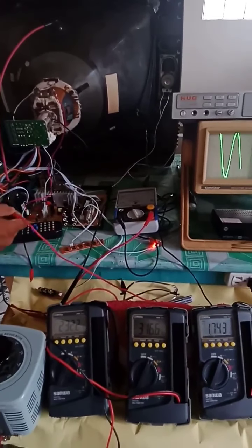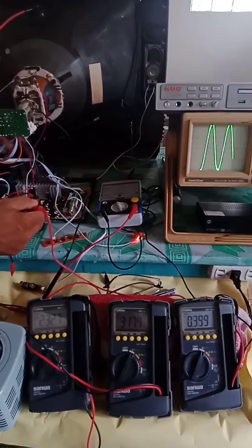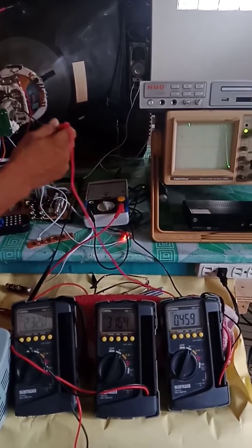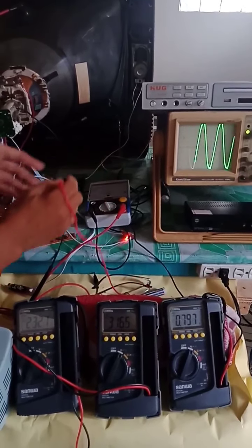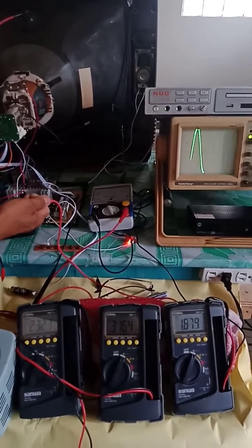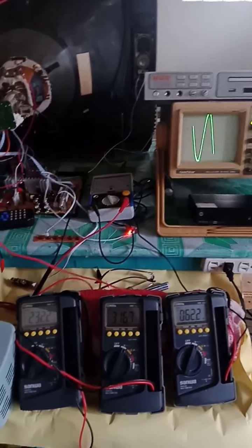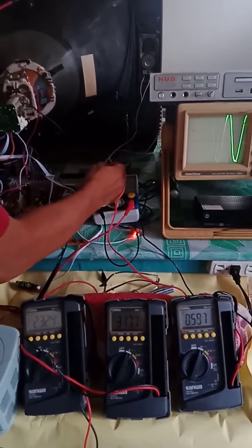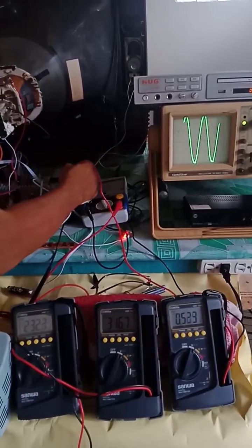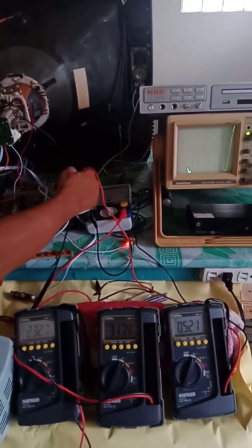For these TV receivers, the voltages for the collector, for the vertical out, and for the sound section are distributed by the low voltage power supply. We can also measure the voltage supplied to the digital circuit, because remember, this is not purely analog. There is an embedment of digital ICs also. For example, this EEPROM is a digital IC. This UOC, or Unified One Chip, is a combination of Jungle and MPU.